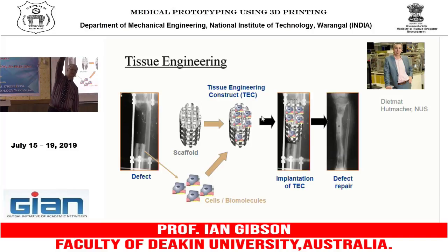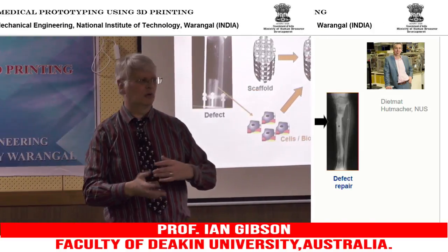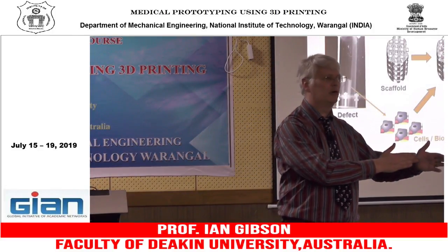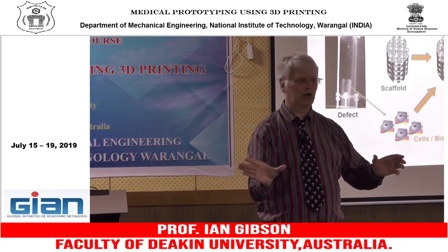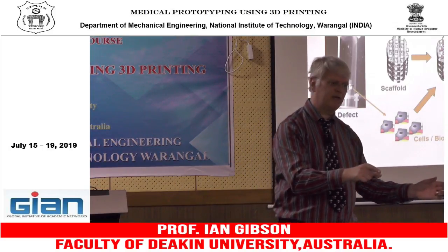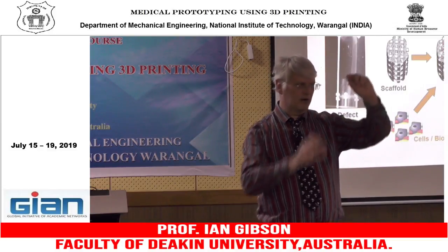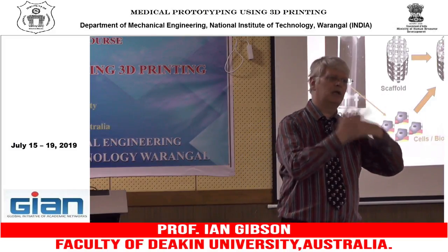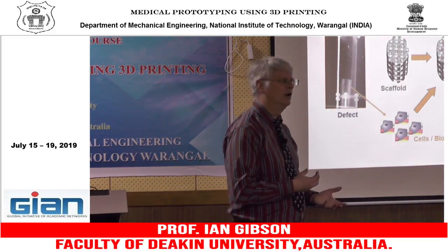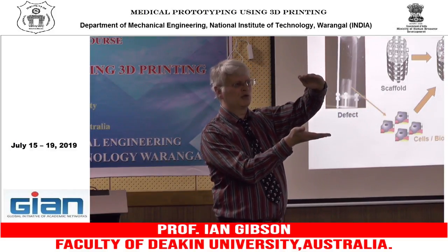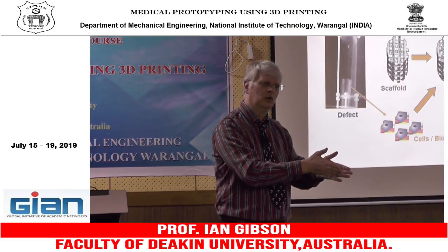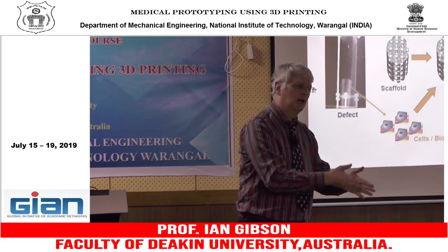It's not a good idea to have a 3D printer with a print head that's this big. Another thing that happens is you usually gradually heat the material up rather than just have one area cold and the other area hot. So in a normal FDM machine, the heating area is this big. That has a significant effect on the flow characteristics of the molten material. So we had a chamber which was this big with heating segments in different regions. We had a nozzle which had a more gradual lead-in, and other factors.